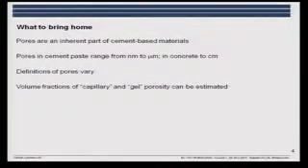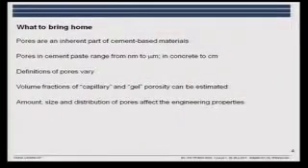And the volume fractions of the solids and the capillary and the gel porosity can be estimated here. The capillary and the gel pores are termed differently depending on which model you're using. And then the amount, the size and distribution of the pores affect the engineering properties. So that's why we're interested in this.